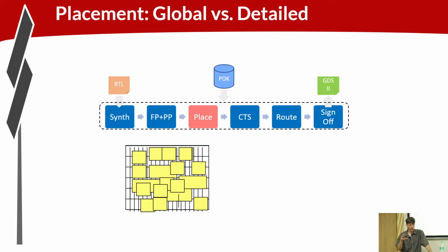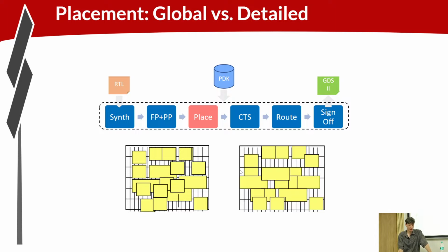So there are multiple steps in the placement process, right? You're starting very high level, and you can sort of picture a bunch of cells connected by rubber bands, and you're stretching that network out to connect it up to the outputs, and then everything just sort of has to kind of fall into place into open space. So you start out with very rough placement, and then kind of refine that down to more specific placement.